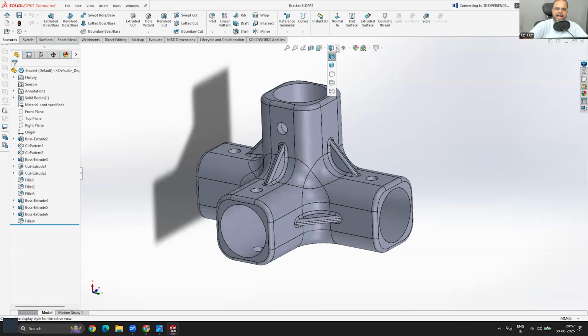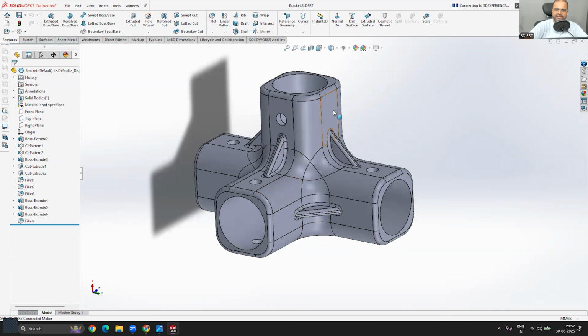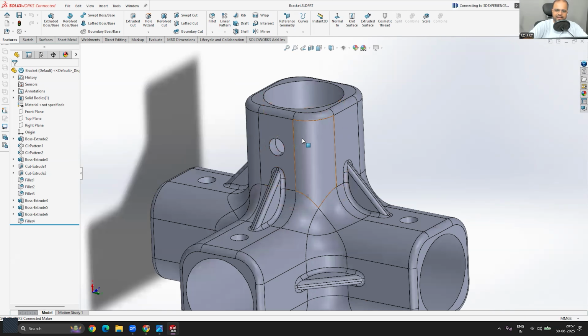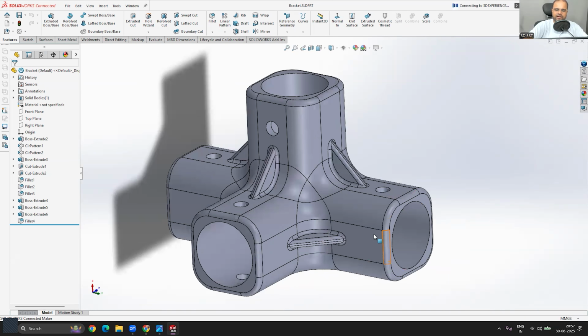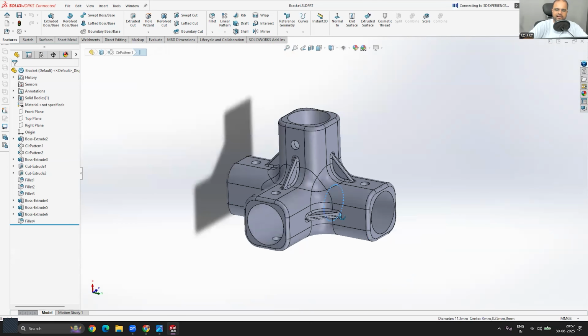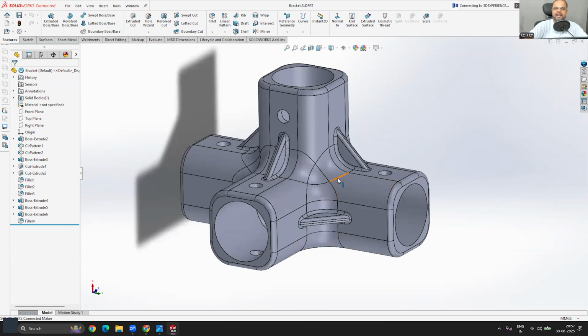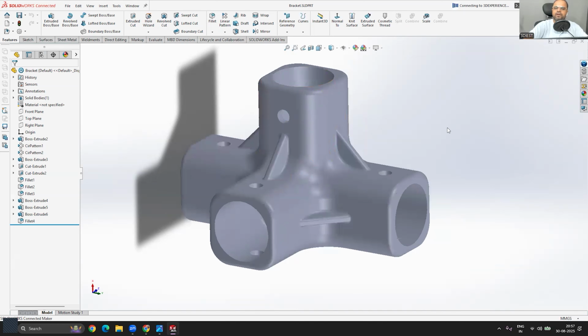Now, next to that, we have this visual style options available over here. So right now, the model style that you can see is known as shaded with visible edges. As you can see, the inside edges of these designs are not visible. For example, these edges are not visible if I am seeing it like this. The internal edges are not visible. So this is the active one right now, shaded with visible edges. Now if we change this to shaded only, the edges will not be visible.